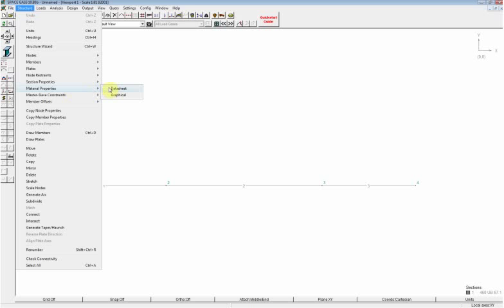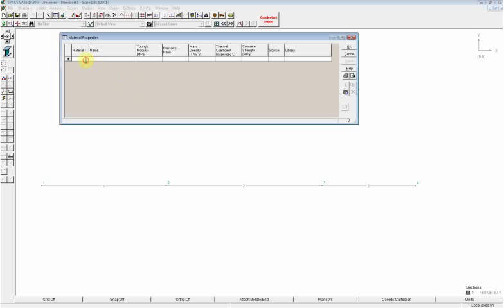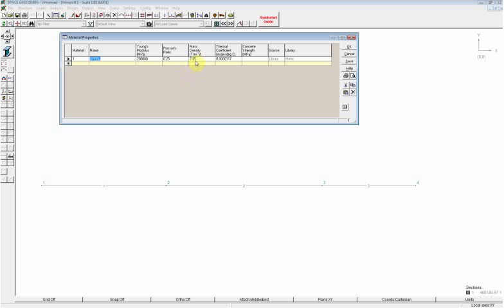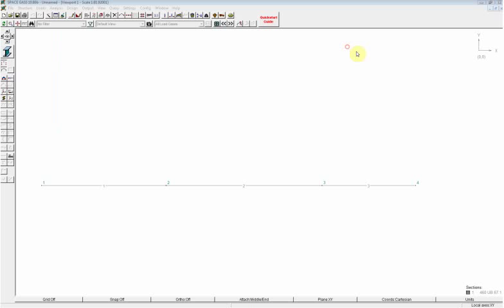Material properties, this is the last one for structures and it's quite important. Hit number 1, and if that doesn't come up, we can just go over to this little booklet. I'm going to click on steel. Now, we don't want steel's self-weight acting on our structure, so we're going to change its density to that. Okay, that's it for structures.